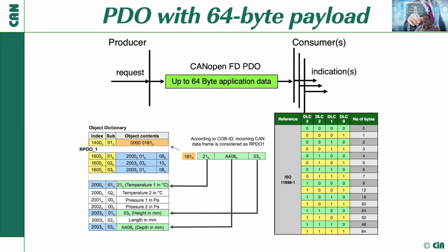Just a small reminder, CAN FD data frames cannot always be adapted to the real required payload, but can only be extended in certain steps. So we see this here. And what does this mean? We should consider padding bytes, so that we do not transmit any rubbish that is occasionally in the memory cells, but only intended data.